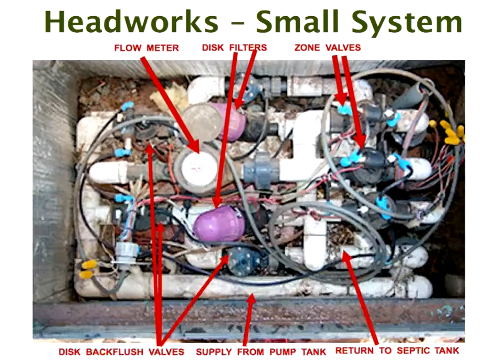All right, this is another headworks. This is a typical headworks system with disc filters. Here are 2 disc filters, one backwashing the other. These systems can run for a long time because they backwash one another efficiently. But again, I would recommend biannual, but at least annual, cleaning.